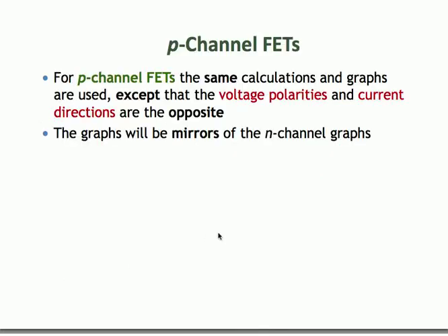Right, so far we have been using n-channel FETs as an example for discussion and calculation, but you also know that p-channel FETs use the same calculations, the same methods, and the same procedures for analysis, except that the voltage polarities and the current directions are the opposite, and therefore the graphs will also be mirror images of the n-channel graphs.